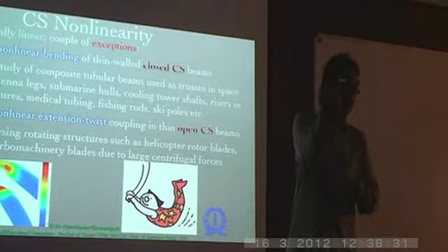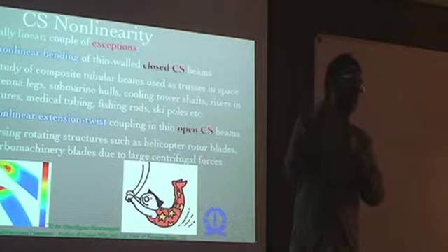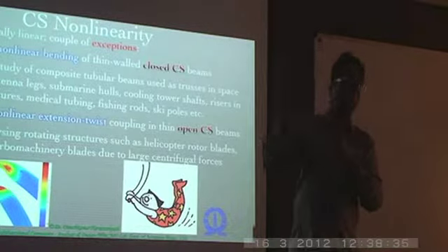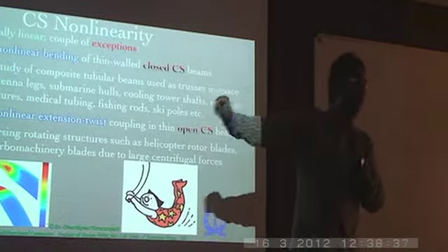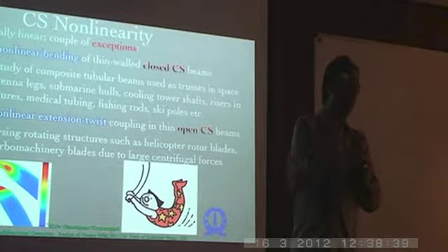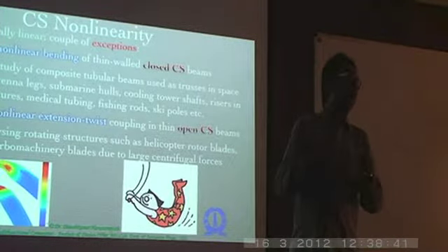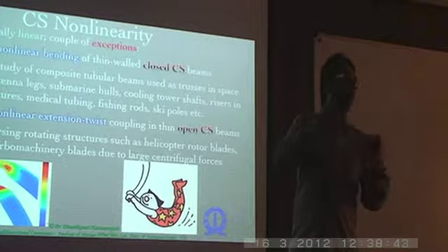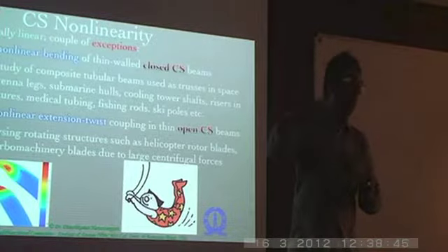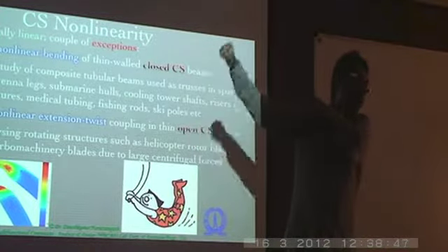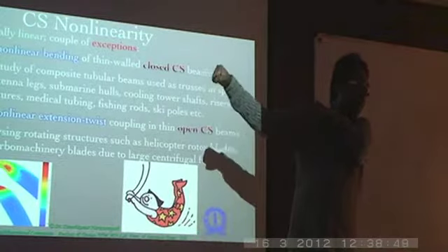So all of those are basically the loads. Now your pitching moment, along with the moment arm that the lift or drag might have with respect to your beam reference line, can cause torsion as well. So that torsion will also be there. So it's a question of which of these loads are dominant. Predominantly your lift distribution bending load will be dominant.